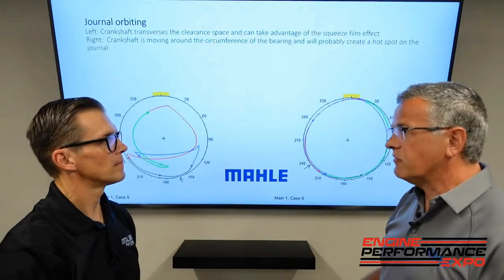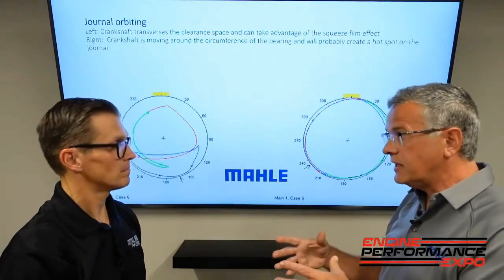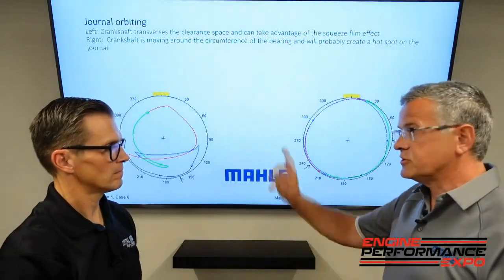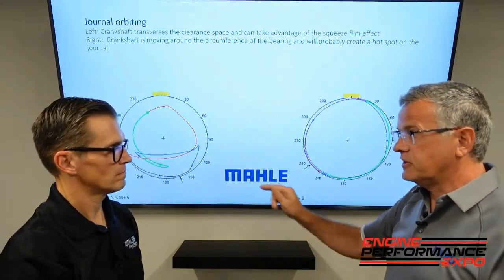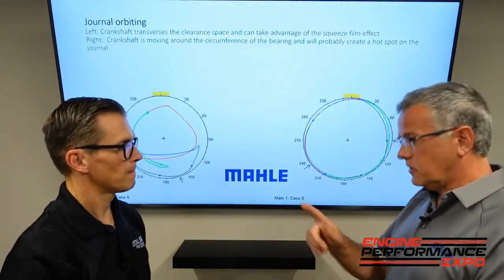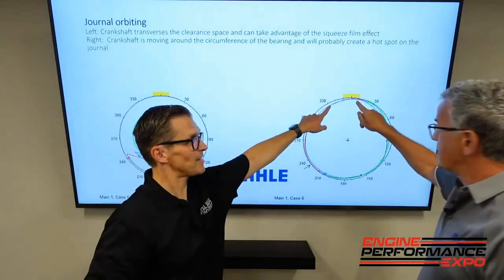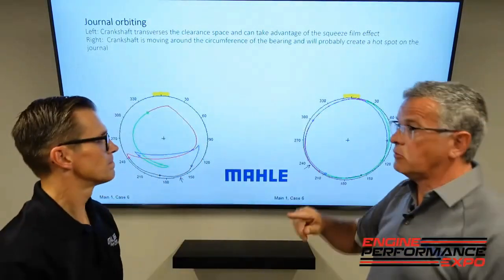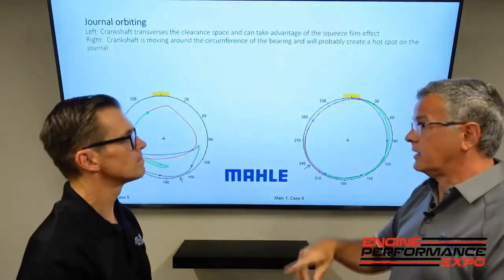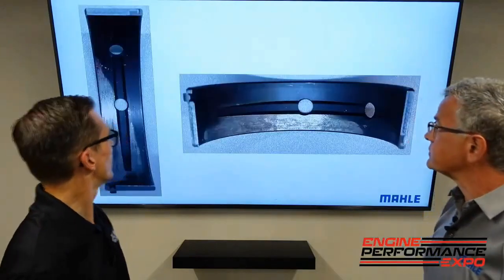Well, I still have customers that have heavy mass rotating, and every time the exhaust stroke, it's trying to throw the piston out the exhaust port. Yeah. And they're getting cap wear. And that's what you're seeing. That's exactly what you're seeing. And now we're going to talk about crank load and the load on that connecting rod bearing.